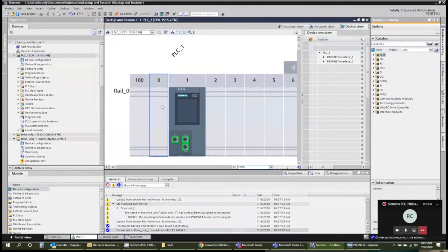Just keep the other thing in mind is Rockwell calls their protocol Ethernet IP, which is extremely confusing because we're used to thinking of Ethernet as the broader communication that we use for all of our computers and that kind of stuff, when technically that's TCP IP. So they're kind of mashing these two terms together, calling it their own, and it's adding a little bit of confusion.